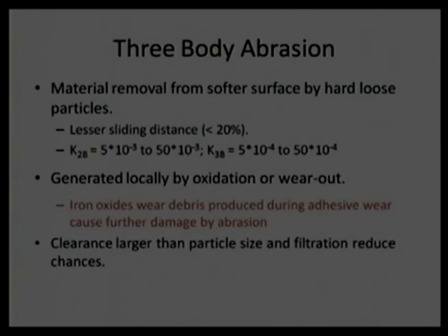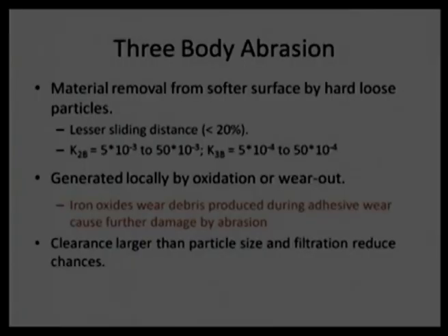Now, we can think about the three body abrasion also. As I mentioned initially, two body abrasion is more harmful compared to three body abrasion, and this slide is giving the reason for that. It says when a particle is detached from the surface, it does not have any rigidity. If you allow movement of the particle, there is a possibility of sliding as well as rolling. And rolling, because it has a lesser coefficient of friction, will be more dominant. For the same force, rolling will be more dominant compared to sliding, if the shape is proper.